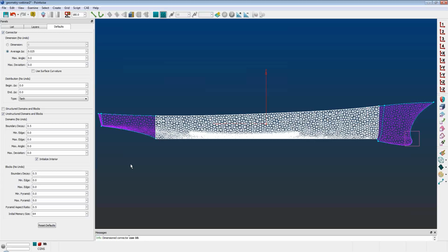Okay, but just to be perfectly clear, you're doing the reproject because sometimes when I read in the same database file that has a slightly different surface compared to the original geometry, I would hope the grid file would automatically be projected onto that. But what you're saying is that if it's slightly changed, or even in a different order in the way the database entities are listed, then you definitely have to go through some sort of glyph script to do a quick regrid of that new geometry.